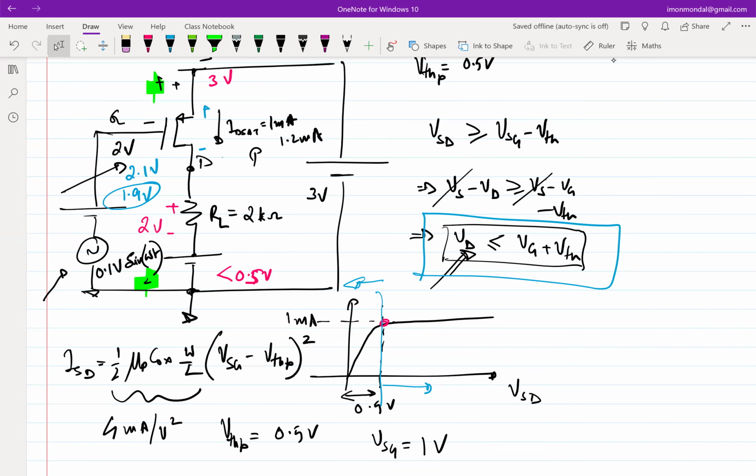But now we have to go back and cross-check: after putting all the loads and voltage sources together, have I tampered with the incremental equivalent, or is it still valid? You start from something, you do some change, and you go back and verify whether what we started off with is still valid or not.